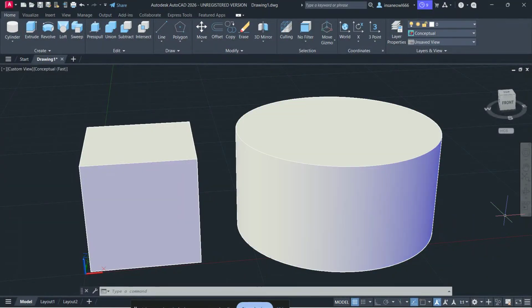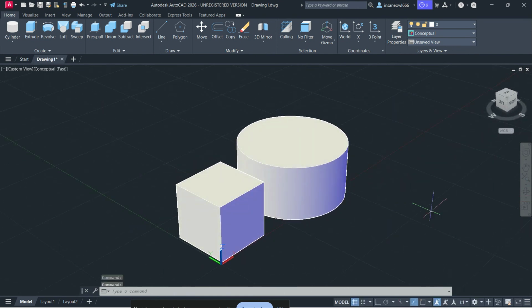If you're seeing AutoCAD error code 84028, you're dealing with a modeling operation problem that usually happens when Autodesk's ShapeManager can't resolve a 3D action like fillet, chamfer, or offset. In simple terms, AutoCAD is trying to calculate a shape, but the resulting geometry becomes mathematically invalid. In this video, I'll show you what causes it and the best ways to fix it step by step.